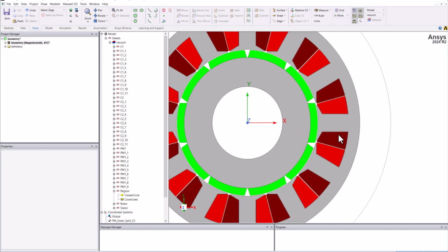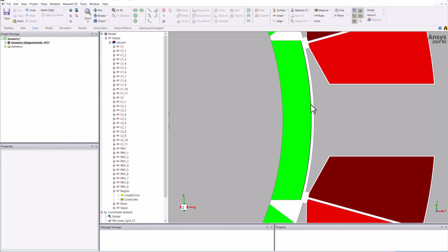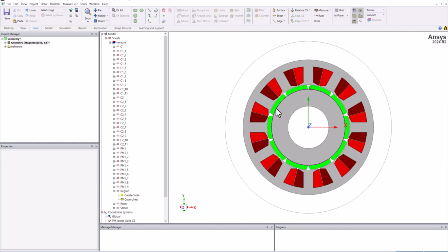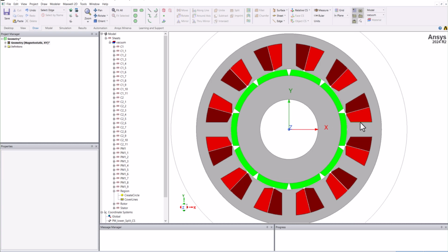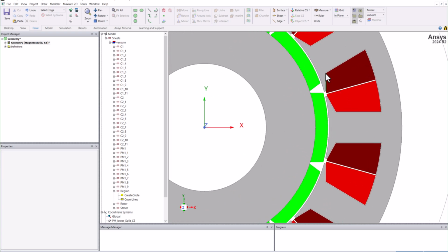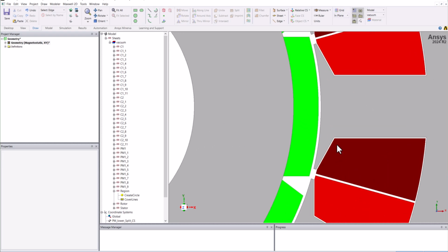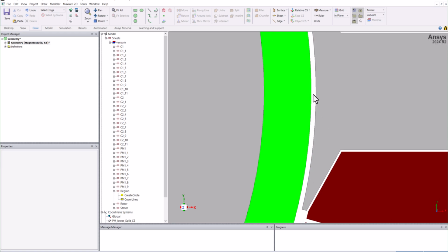Now as I mentioned earlier, we have to create a rotational band also. We know that this rotor is going to rotate. Maxwell will not be able to understand just by the naming that if it is named rotor it will be rotating. For Maxwell this is just a common geometry that it has to mesh and solve according to the given excitations and boundary conditions. So we have to make Maxwell understand that we will be making a rotational circle in which all the objects will be rotating.